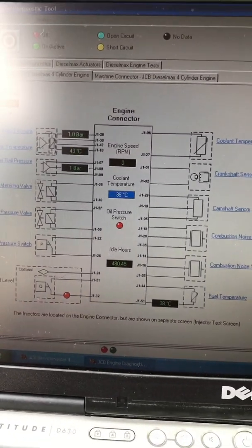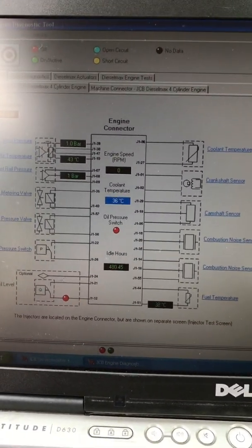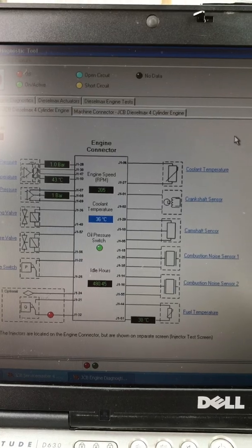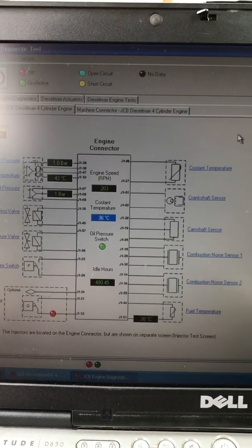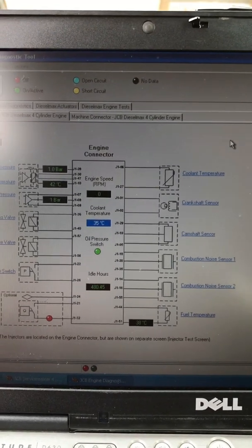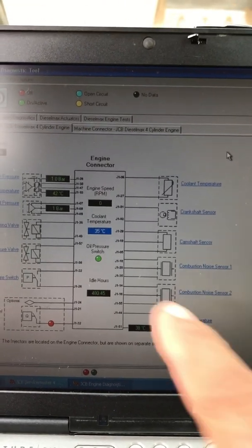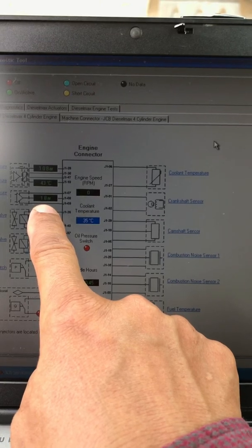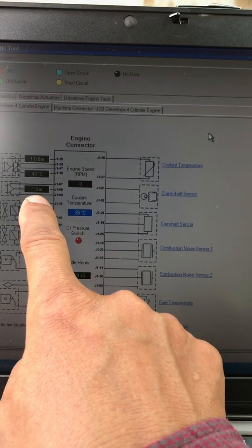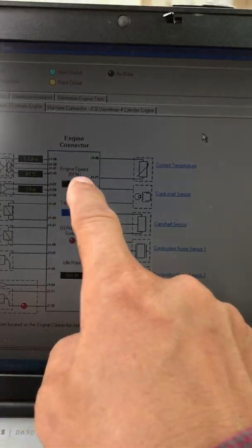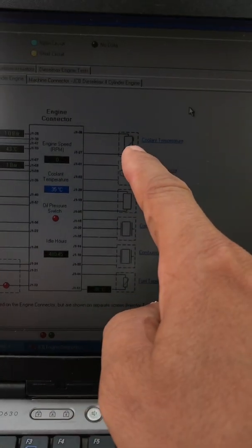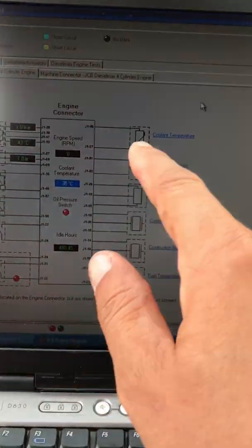Right now I will start the engine and look here. When I crank the engine, the rail pressure stays the same, 1 to 3. No pressure rise, no pressure increase. So that's why the engine cannot start. Actually this must be more than 250 bar. At least we need 250 bar. Then when starting the engine, it reaches 390 to 400 bar while the engine is starting.